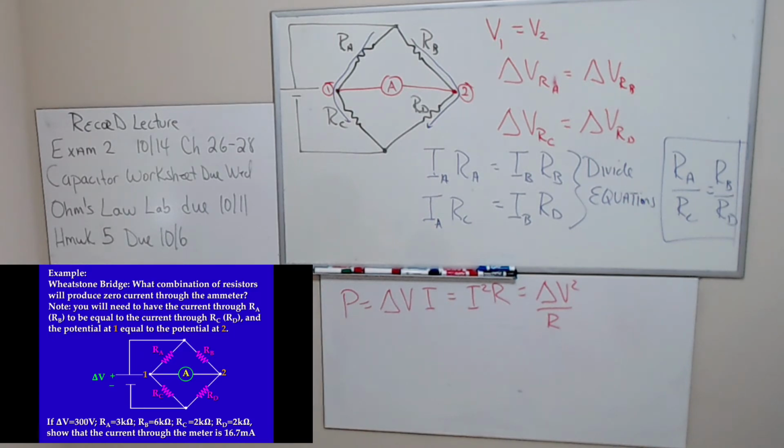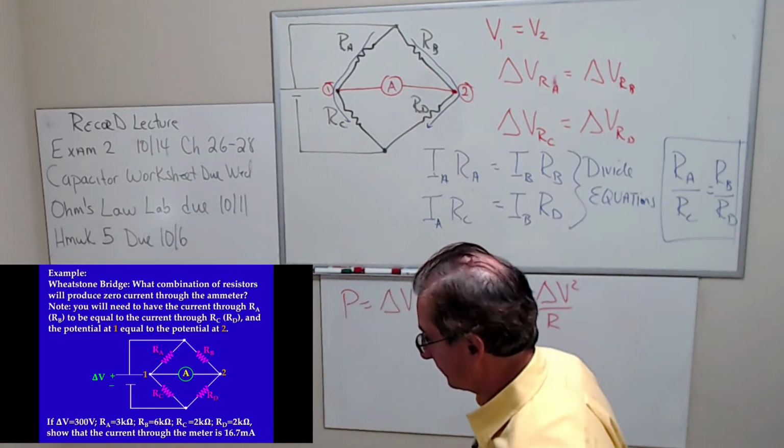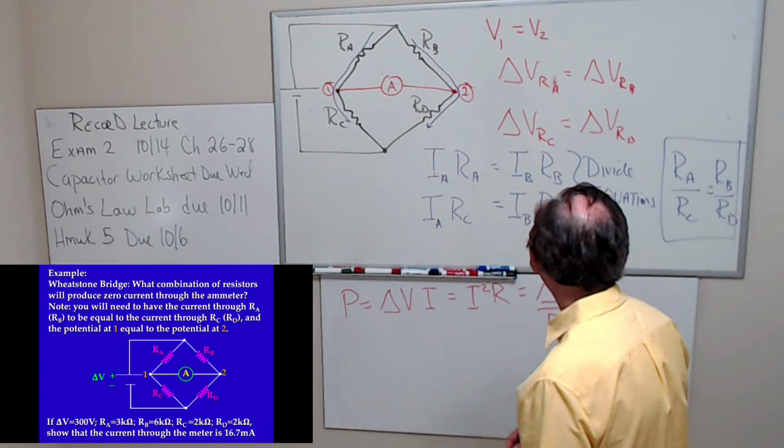So basically in a galvanometer, if you run a current through a coil, you can get a dial to rotate. Of course, we've got to talk about that in the next chapter. If you run a current, you'll get a magnetic field. And if you put a coil in a magnetic field, the coil will want to rotate. So actually, a galvanometer is more sensitive, and in reality, that's what you use. Are we okay with this?